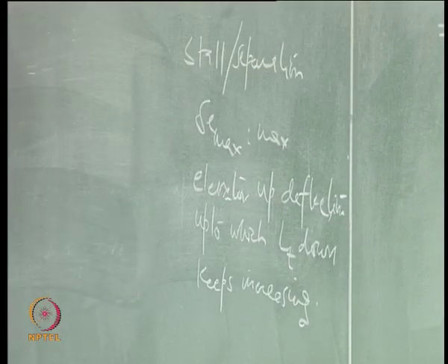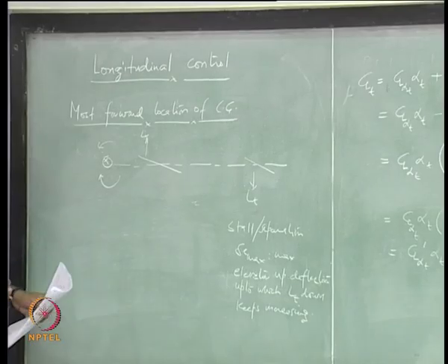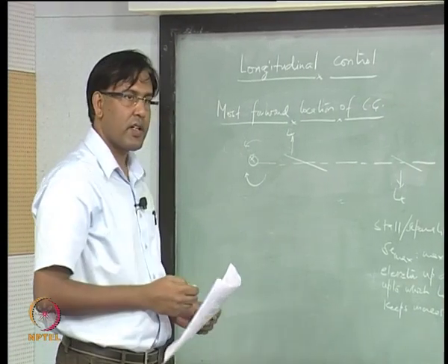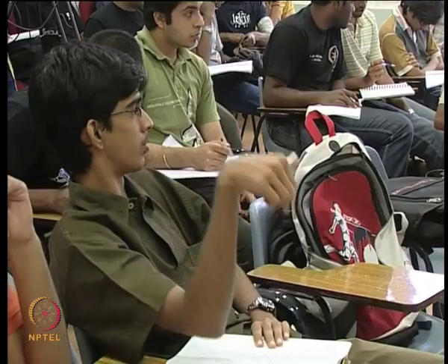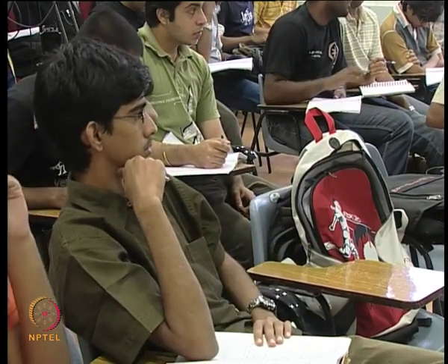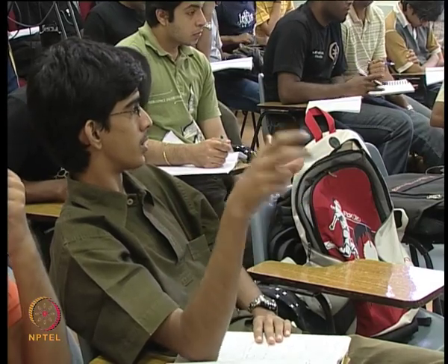So in this configuration, the wing has to produce additional lift, because there's a component of lift downward by the tail, we have to balance the weight. So we have a stability versus wing load.